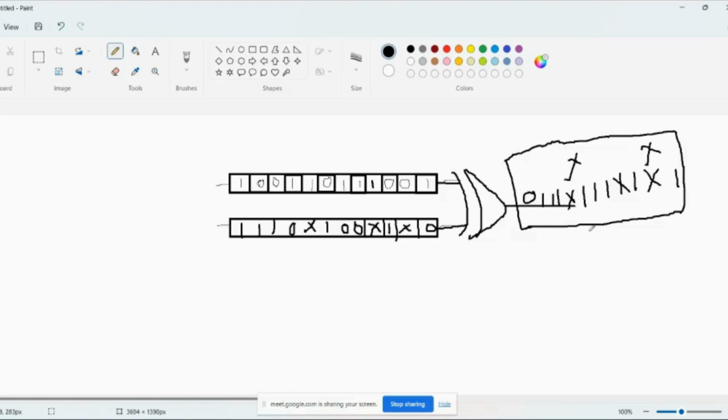So we always make sure the pattern has a solid 0 or 1. On a physical level, the tool doesn't understand X. Not the tool, the chip will understand X. It will consider it as metastable. So when you have metastable data, not stable data, your pattern will fail.